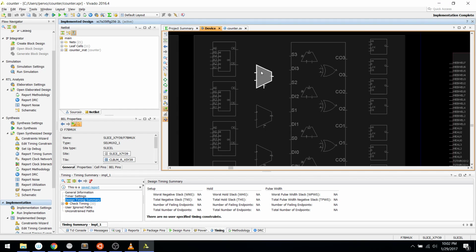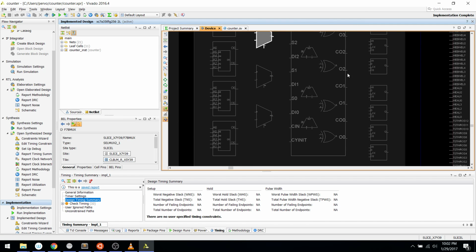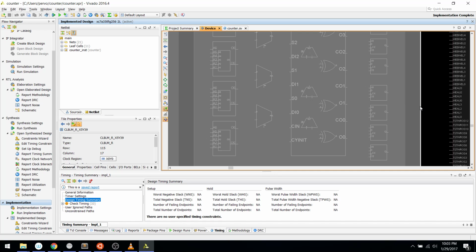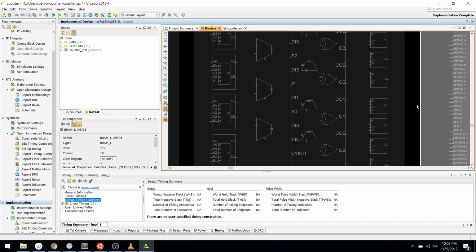Beyond that, you have some other functionality here. You have this mux, which I'm not going to go into too much detail on, but basically you can control how some of these things are routed. There's also this thing that can select between the output of this thing and another external input. Then there's this thing here called the carry chain. You can't see the internal connectivity, but this basically goes bottom to top, and it's an efficient way of implementing ripple carry adders, but can also be hacked to do things that are not quite ripple carry adders.